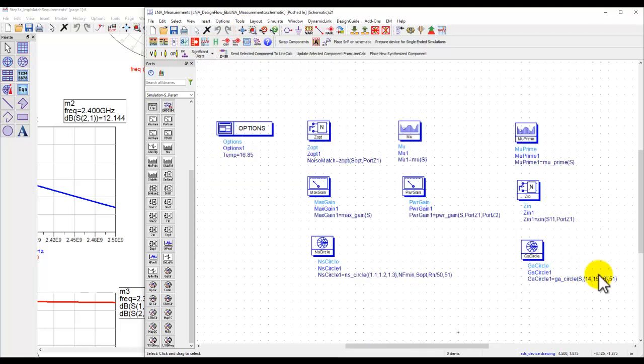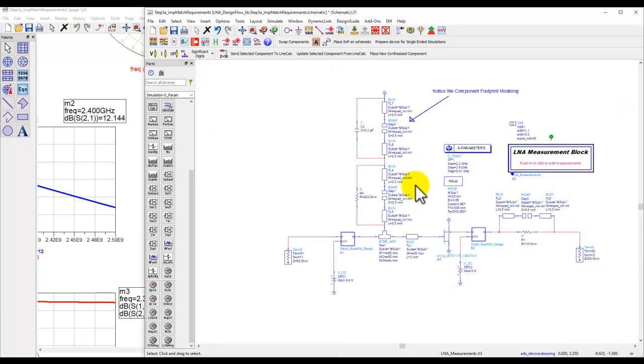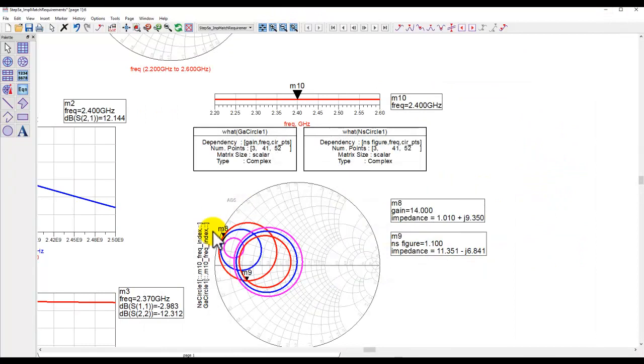Again, you can set it as per your expectation, what you're looking at. I have set it to 14 to 16 because I minimum needed 14 dB gain. And I just wanted to have an additional 2 circles to see which is the area which might give me a little additional cushion on top of 14 dB to account for any additional loss which I may have in the further design step. All right, so this is how it is set up. And let's go back to data display.